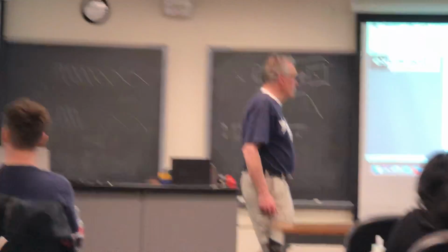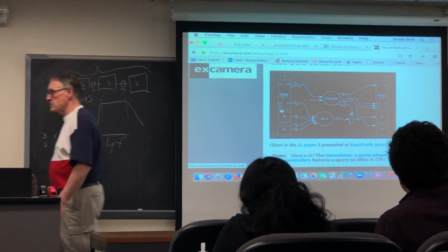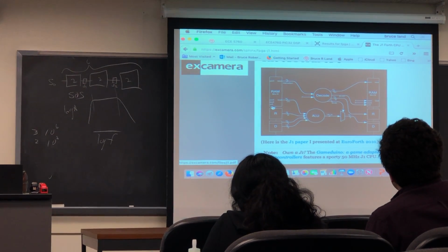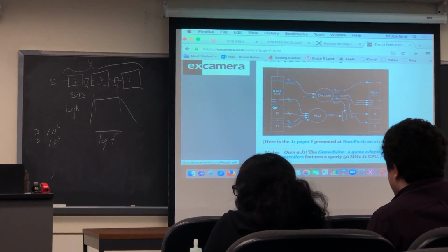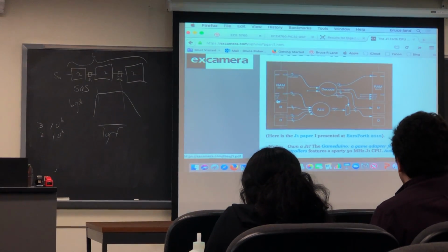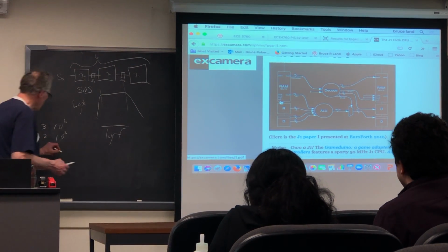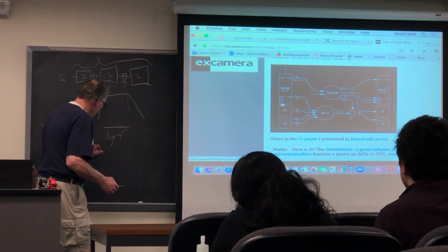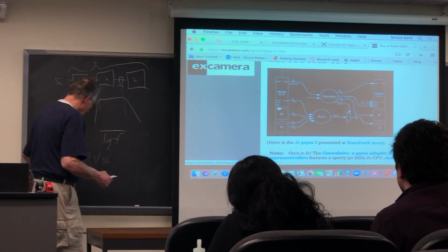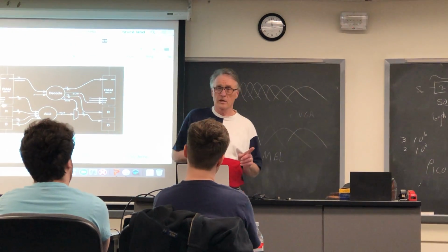You do only stack manipulations, but it's extremely small, and it's in open source Verilog. Be fun to port. There's also, you're familiar with RISC-V? You've heard that around. There's a small implementation of RISC-V called PicoRV32, P-I-C-O. That is a cut down version of the RISC-V that I believe still runs the GCC toolchain.